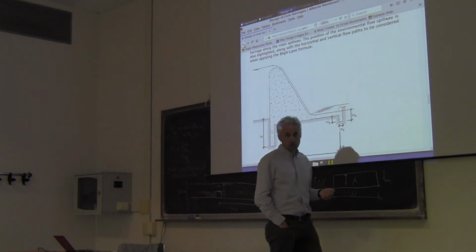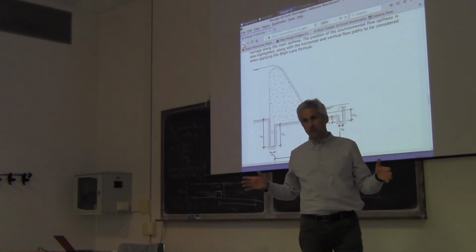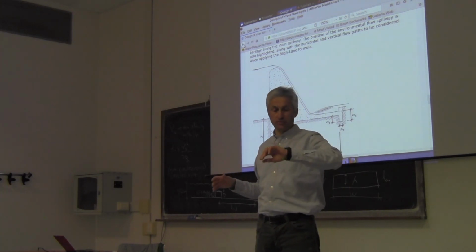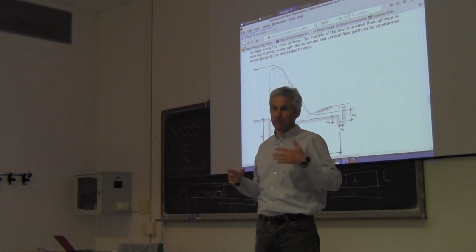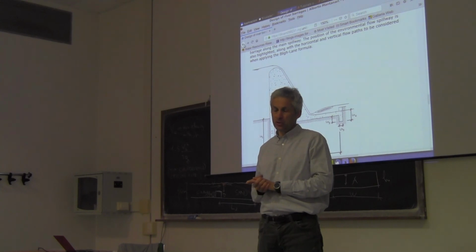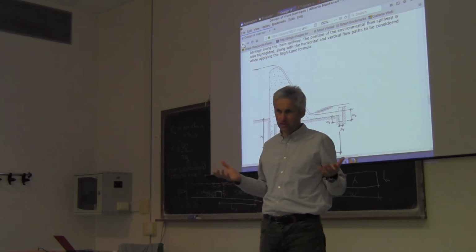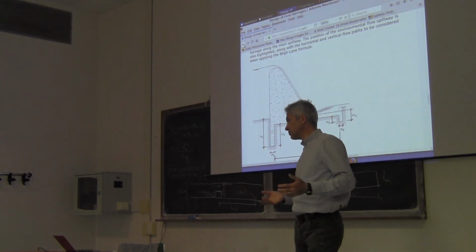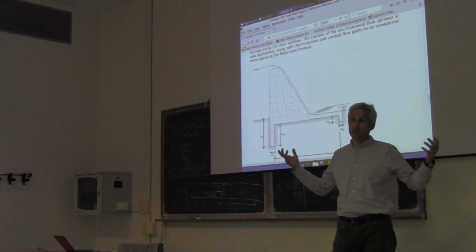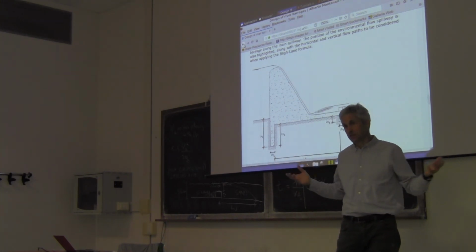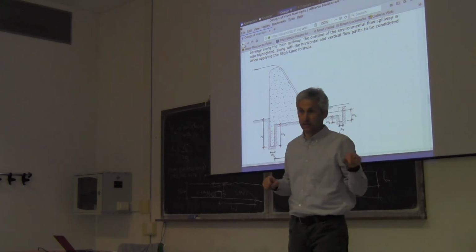You can avoid erosion by placing big boulders downstream, and this is the solution that is most frequently adopted because it's environmentally friendly, and also it's not very expensive. It is subject to uncertainty because what is the size of the boulders? This is a big question mark.